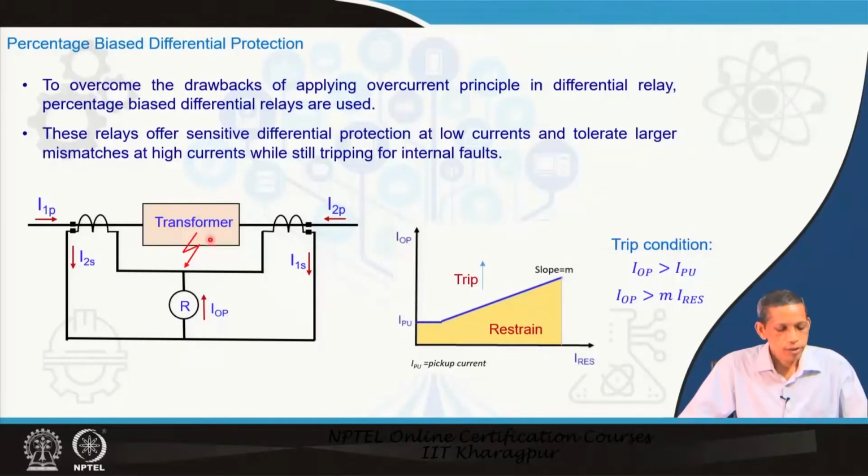So, what is being done here for these kinds of connections is that we have the relay characteristic, a very basic one first, and then we will go for further details: the differential current versus the corresponding restraining current. Agree? This restraining current is related to the more current through these CTs, and then the corresponding opposition to the operating current will be more and more.